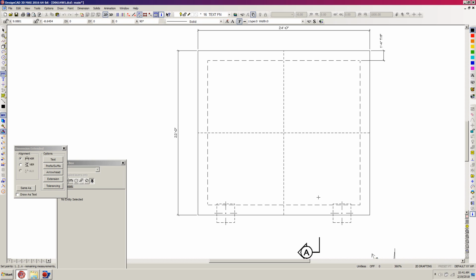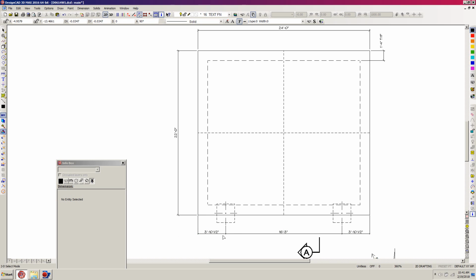to run horizontally. So I'm going to right click on the corner, right click to the center line here, right click to the other center line, and right click to the other corner, and pull those down about like so. And then I'm going to left click there and hit my scroll button. And so now we have those footings laid out relative to the corners of the actual building.